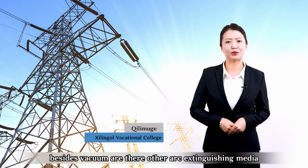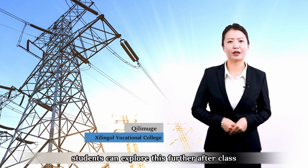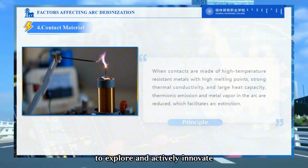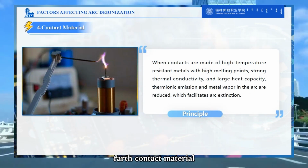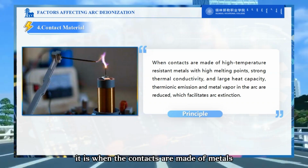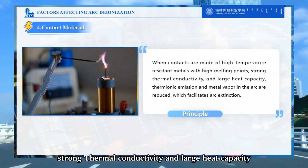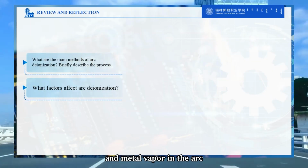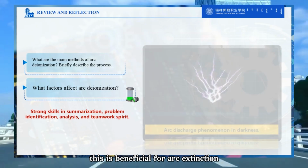Besides vacuum, are there other arc extinguishing media? Students can explore this further after class. Cultivate a spirit of daring to explore and actively innovate. Fourth, contact material. The contacts are made of metals that have a high melting point, strong thermal conductivity, and large heat capacity, and are high temperature resistant. This reduces thermionic emission and metal vapor in the arc. This is beneficial for arc extinction.